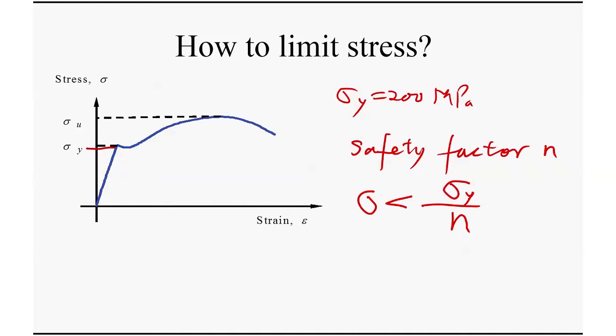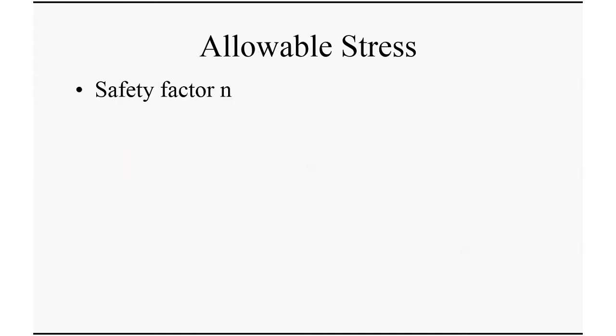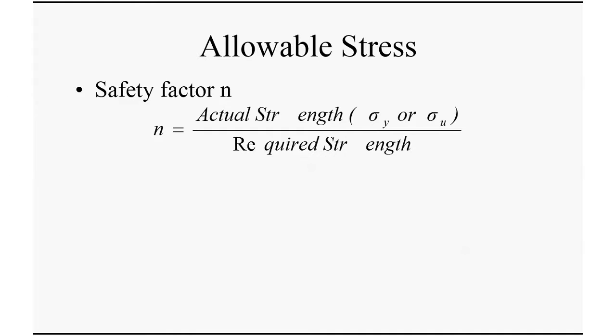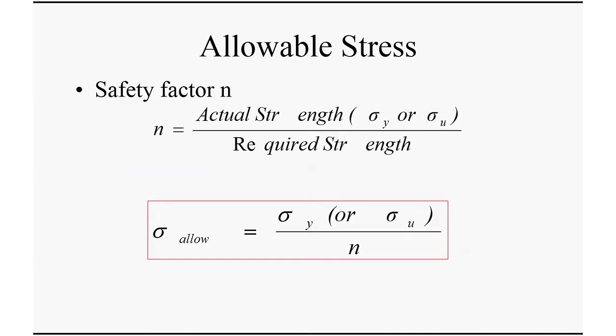You will basically calculate this stress, what we call sigma. Actually, I think it's next slide. So the allowable stress. And here is the equation. Okay. So we calculate this value, what we call allowable stress. Basically, that's the limit for my design.